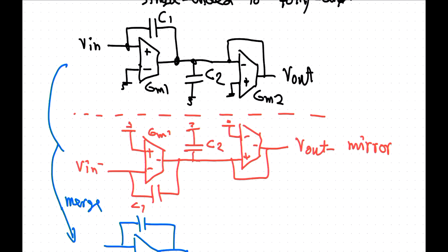But we don't really want to do that. It doesn't have the good properties of a fully differential circuit, because we have the whole processing going in two different channels essentially. What we really wanted is common mode rejection in every single stage. We don't really have that here. So that's why we want to merge these two into one circuit, and that has common mode rejection in itself.